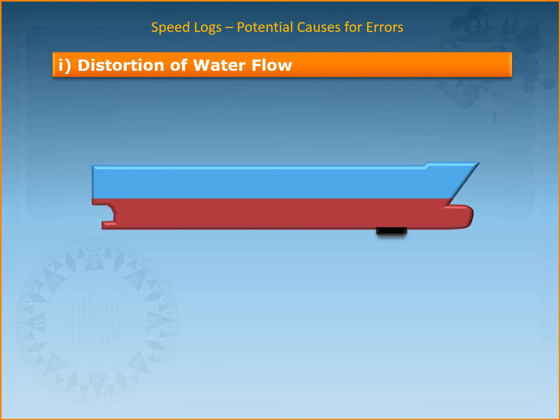Finally, we discuss the sighting of the logs and how they cause potential errors. Generally speed logs are very reliable, but you must understand that speed measurement errors can arise and under what circumstances the log is likely to be inaccurate. This is especially important for electromagnetic logs, where the measurement of the speed depends on the flow of the water across it.